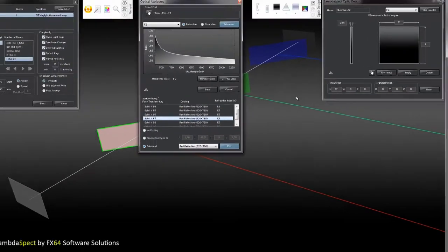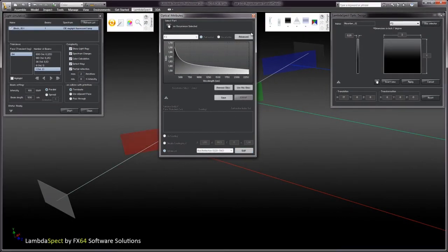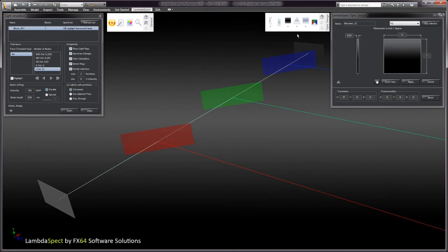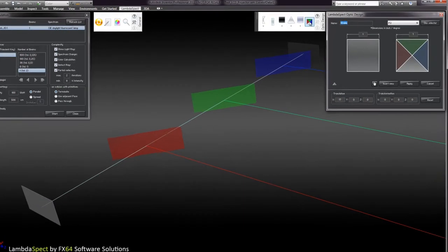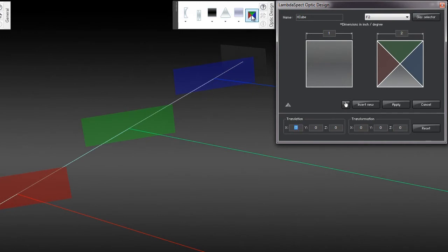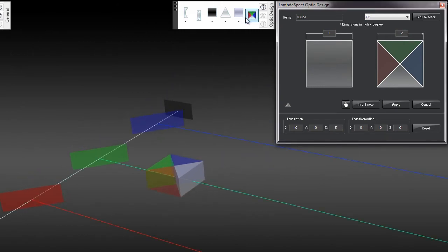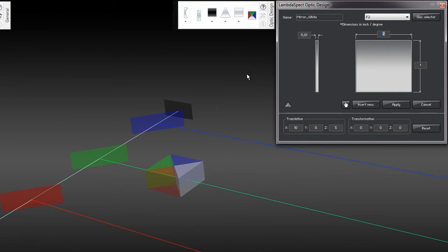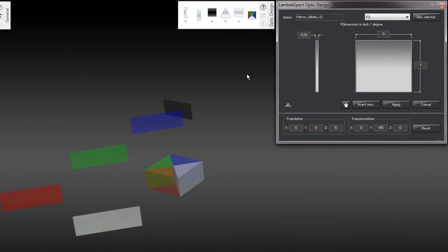The filtered red, green and blue rays are used, for example, to light the RGB panels of an LCD sensor array. To merge those beams, we use an X-Cube. The X-Cube consists of 4 prisms with different coatings that combine red, green and blue input rays into a mixed output ray. To redirect the blue and red beams into the X-Cube, we use 2 high reflective mirrors. By the way, you can put all of those optical properties, for example coatings, manually on your existing parts and systems and change the way of their reflective behavior.